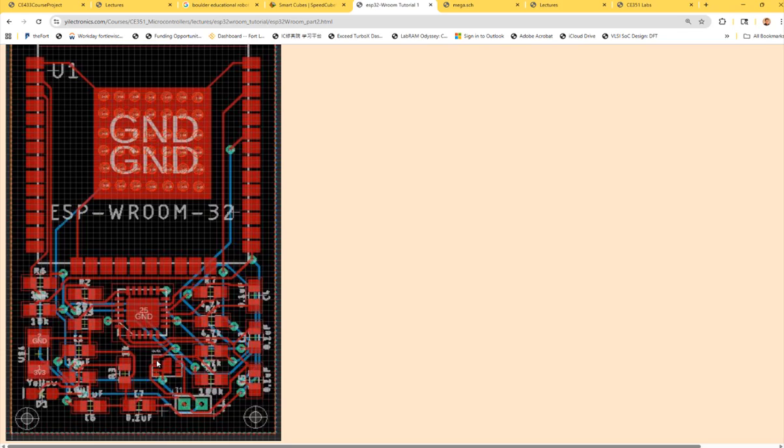Some of the three cell batteries are 11.1 volts. So they'll tell you the 3-cell LiPo battery has 3 cells in it, stacked onto each other, eventually giving you 3 times 3.7. So 3.7 volts per cell, but all the components require 3.3 volts as a power supply, right?